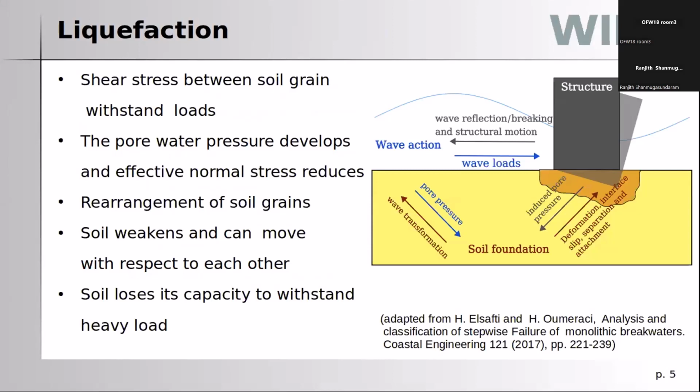So what do we mean by liquefaction? Liquefaction is the process in which the soil behaves like a highly viscous fluid, and this happens mainly in the case of saturated soil, where the soil completely lacks air and is completely filled with fluid. Whenever there are loading waves on the top, the seabed is pushed, and the pore space between the soil grains is completely occupied by water. When there is a load from the waves, the pressure between the soil grains, which is the pore water pressure, starts to increase.